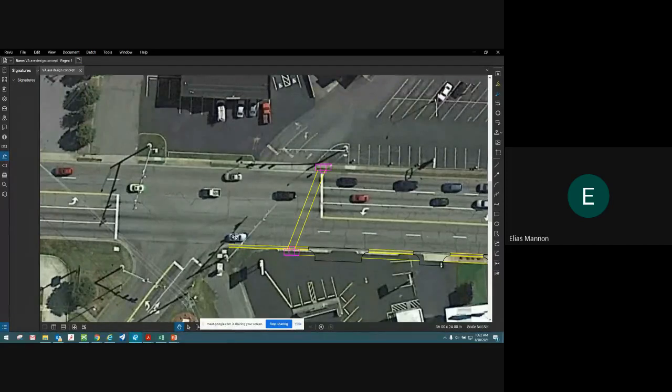And so we had to go back and figure out what the best configuration of this crosswalk should be. And as we were doing that, we reviewed our own design standards, and in the road design manual, it says that whenever you alter one ped accommodation at an intersection, you have to accommodate all the other legs of that intersection as well, all the other segments. And so that meant that we would have to provide a crossing of this side street as well. So that added cost to the project.